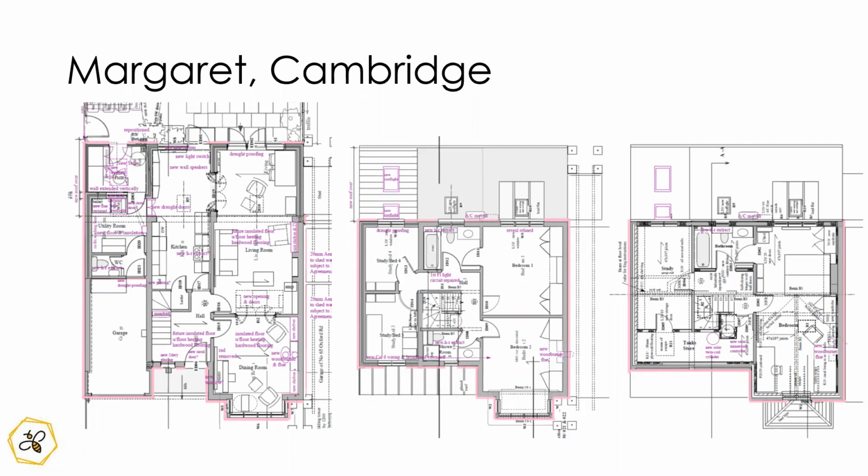Another question was, we've had the boiler way in the back in the utility room. It used to be in the kitchen, and then we've put the tank right up in the loft, so they're miles apart. Does that matter? Should we be looking to reorganize that? It does. I'm looking at the drawings and being a bit concerned, because even if you put the heat pump in near the front of your garden, that is a long way to get all the way up to the tank.